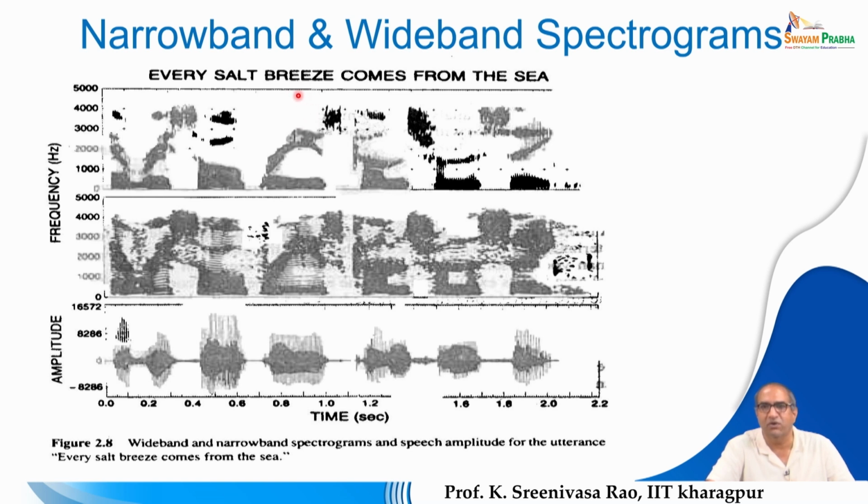It's not that there is no frequency component, the frequencies may be there, but they have very insignificant energy. The energy associated with these frequency components may be 1000 times lower than the energy associated with this one. So when you normalize from maximum to minimum, these frequency components are observed to be white with respect to energy, whereas these are observed to be somewhat gray, and again there are certain frequency components that are very dark.